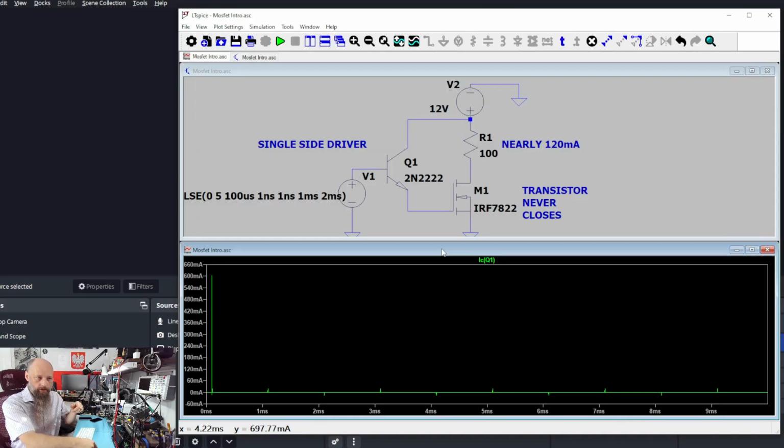You will see that the transistor will open as you touch the positive, and if you touch the negative, the transistor will close. Now, the resistance of our body is, I don't remember, some megaohms, a very high resistance. But that's enough to charge and discharge the gate. So when measuring MOSFETs during the operation of the device, keep that in mind, because you can completely blow the device just by measuring the gate of the MOSFET.